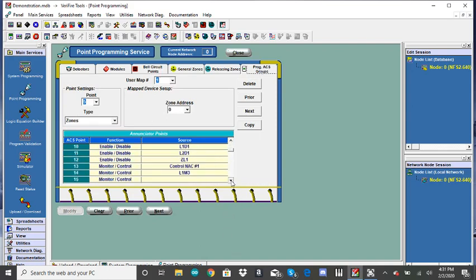So you can see that there are a lot more points than 24 on this particular map. You can see it goes up to 64 because I believe that's the largest size individual ACM annunciator that you can have, is 64 point. I got the 24 point because it has switches on it, and I wanted switches for enable, disable, and what have you.